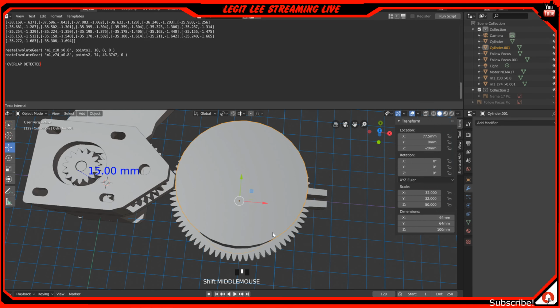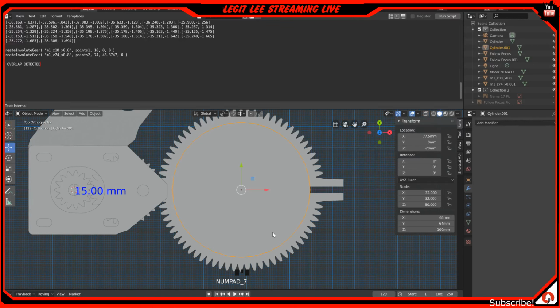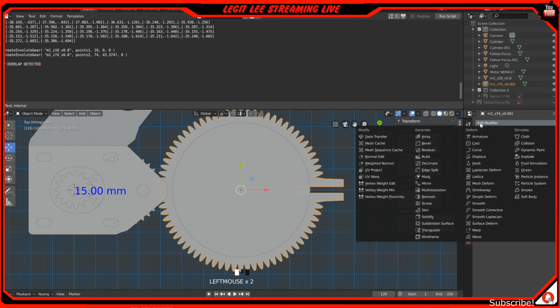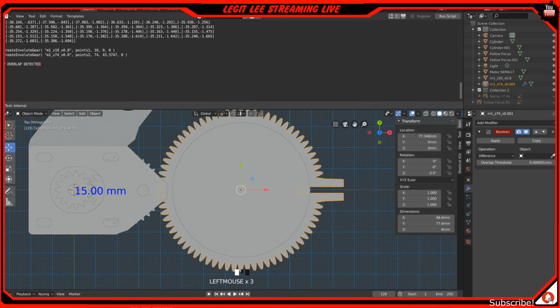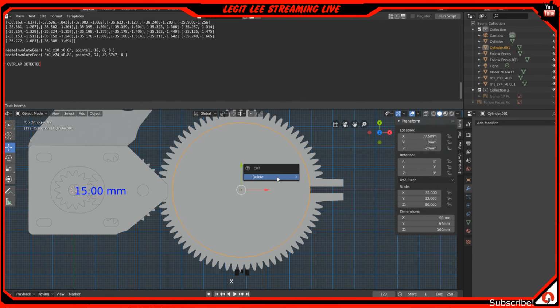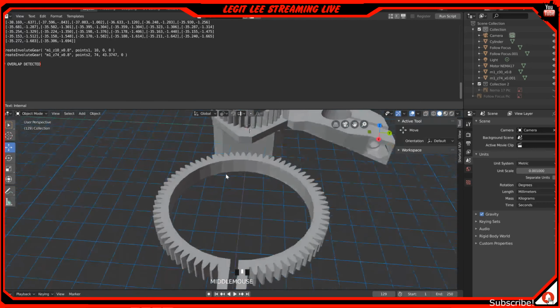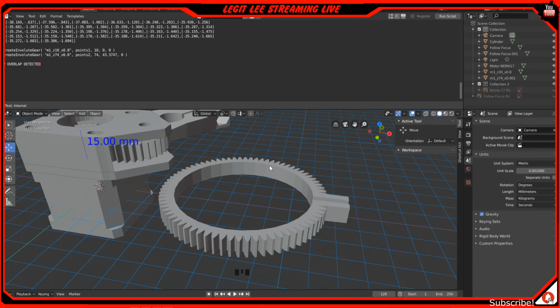Same thing with this guy. But we're going to want to change the vertices. I want to make sure it's just not some weird... Well, no, the vertices, I guess, is okay. It doesn't have to be completely flat. Because that'll help with crushing onto the lens and grabbing that stuff. So, we could leave it that way. I think it'll be alright. So if I hit this, add another modifier, Boolean, grab this dropper, click on this guy, hit apply, go ahead and delete this guy, and voila, we have our ring. Ooh, that ring is amazing.